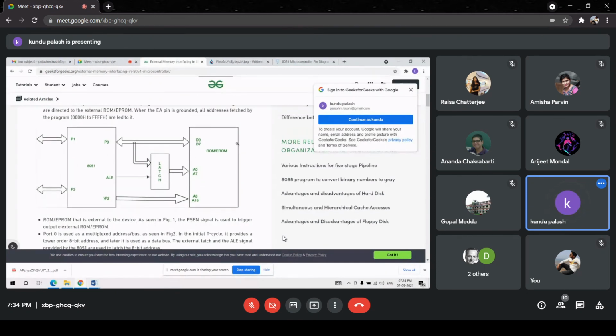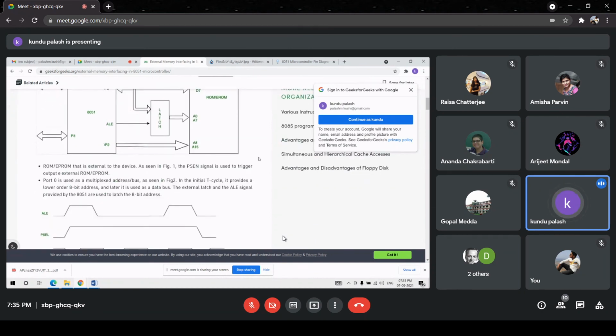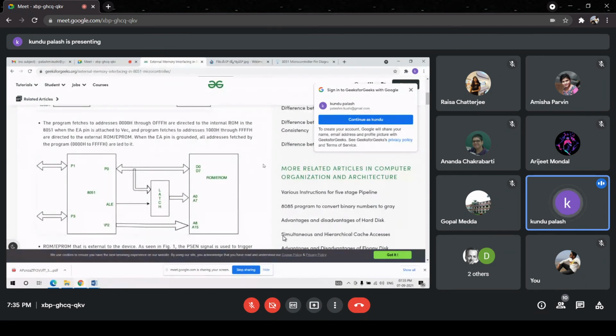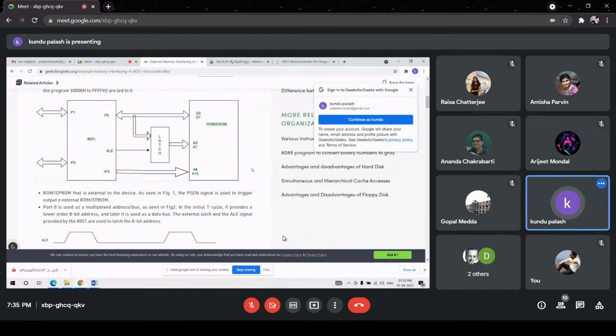Now, this is of which type of memory? Size is 64 kilobyte. But if it is required to design an interfacing circuit with 32 kilobyte memory space, which is partitioned or split into 16 kilobytes and 16 kilobytes, then definitely there must be a decoding logic and other things. So I will give you different memory interfacing problems so that you can design.